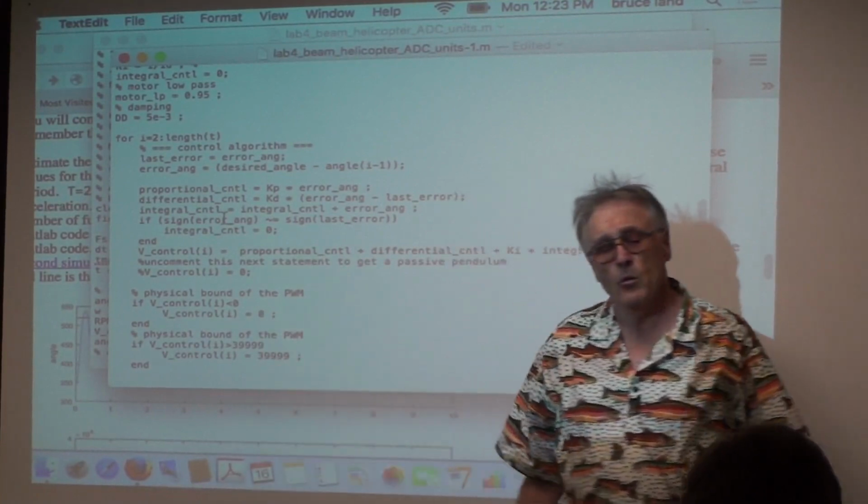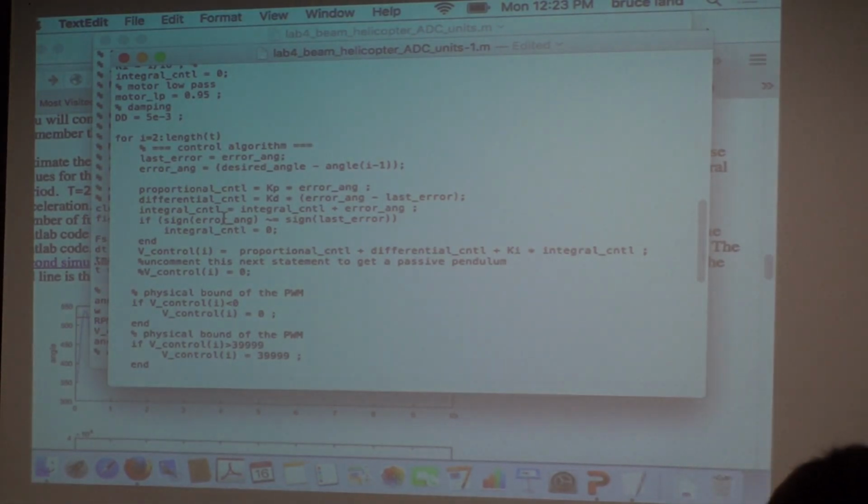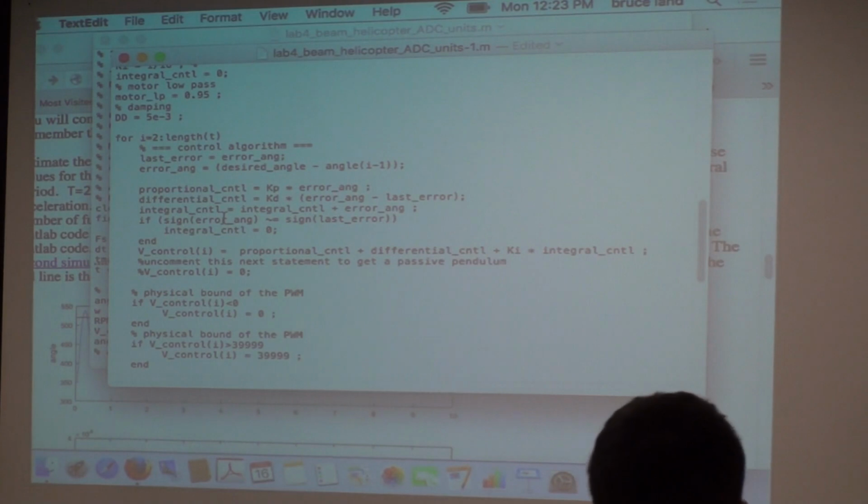And secondly, if the number calculated for the output gets greater than the maximum that the PWM can sustain, we better not wrap, because that'll produce a lower RPM, not a higher RPM.